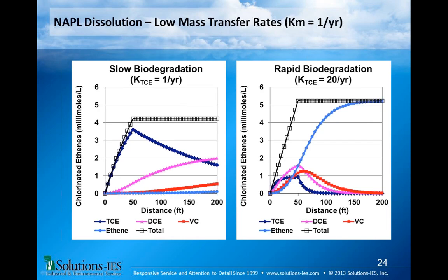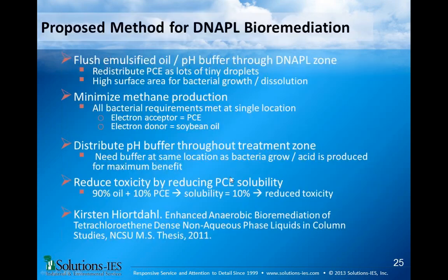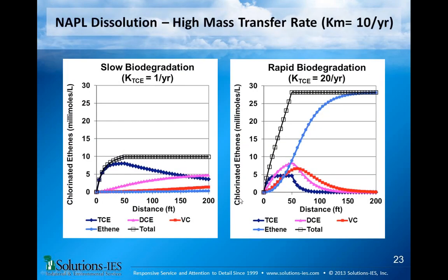The other thing is, based on what I haven't shown you, the chloride data. By the time we're here, it looks like we've dechlorinated a lot of the PCE. It's possible a fair amount of the DCE coming out here was actually produced sometime in the past and is sorbed inside the vegetable oil. So we believe that the PCE toxicity has been significantly reduced by here, and that's why we're getting this gradual increase, or at least that's the best explanation I have. Any other questions?